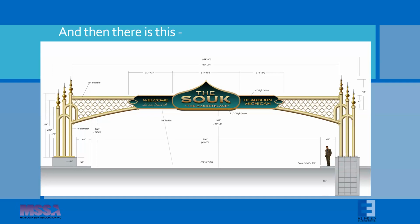And so only 15% of the load is being transferred through the middle and outer poles. If you wanted to just have a very cost-effective sign, you would actually reduce the diameters of those center and outer poles, and it would result in a cost savings. Except a design like this is obviously visually important to the client and to the architect.